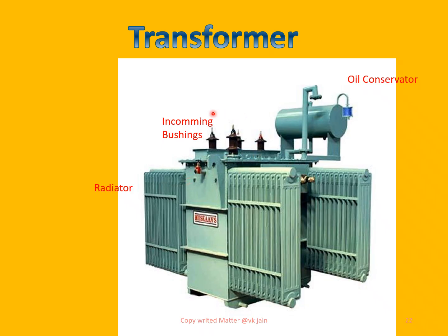Now when the power is on, the windings provided in the transformer, these are the windings, inside this, and I'll show you the windings in the next slide, are getting warm, and the oil circulated therein is sent outside for cooling purposes.